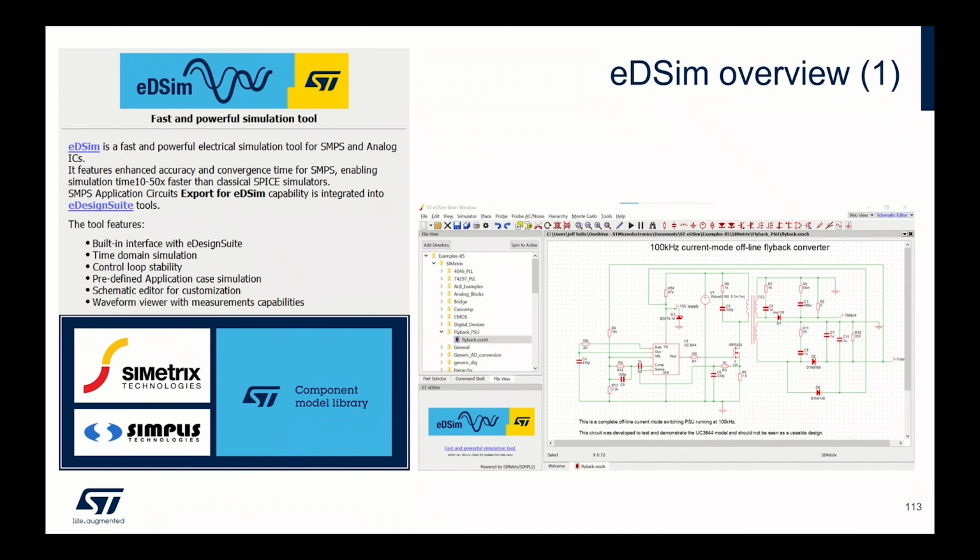So maybe a few of you may have tried to simulate a buck regulator in PSpice. First of all, it can be very slow, so the simulations may take a long time to spit out a result, or they may not even converge. So the simulation may just crash at the very end, and you may not have an actual result. That's the reason why Simplis is the right tool to simulate switching mode power supplies. The tool is completely free. It's actually a tool that ST provides to its customer base.